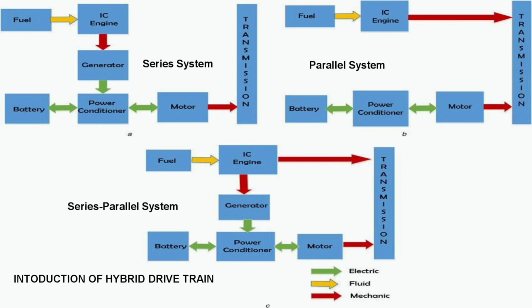So the complex hybrid electric vehicle configurations are 2 types: front hybrid, rear electric and rear hybrid. Both configurations have 6 modes of operation. Mode 1, during startup, the required traction power is delivered by the EMs and the engine is in off mode.